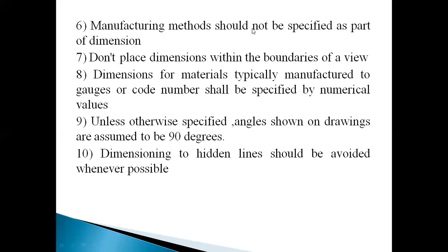The use of reference dimensions on a drawing should be minimized. Don't place dimensions within the boundaries of a view. Dimensions for materials typically manufactured to gauges or code numbers shall be specified by numerical values.